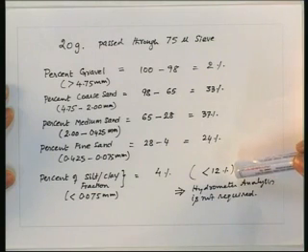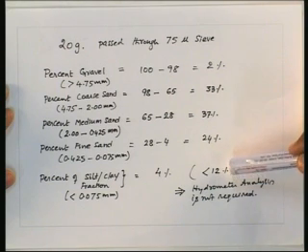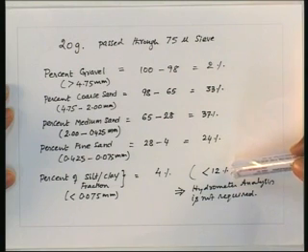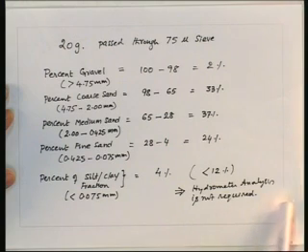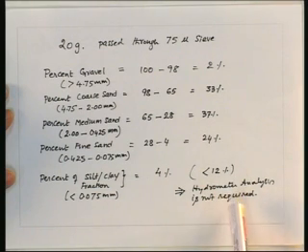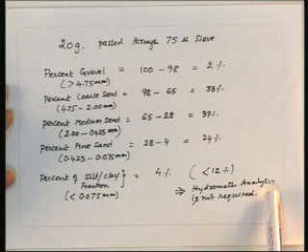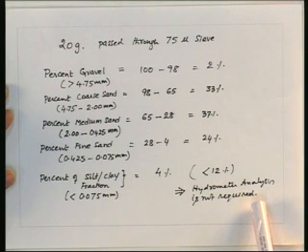Suppose the percentage of silt and clay fraction passing through 75 micron is less than 12%, then the hydrometer analysis, or wet mechanical method of analysis, is not required, that is, the sedimentation analysis is not required. But if the percentage of fines is greater than 12%, then it is required to determine the fine grained fraction size, to assess the percentage of clay particles and silt particles. That can be determined by hydrometer analysis.